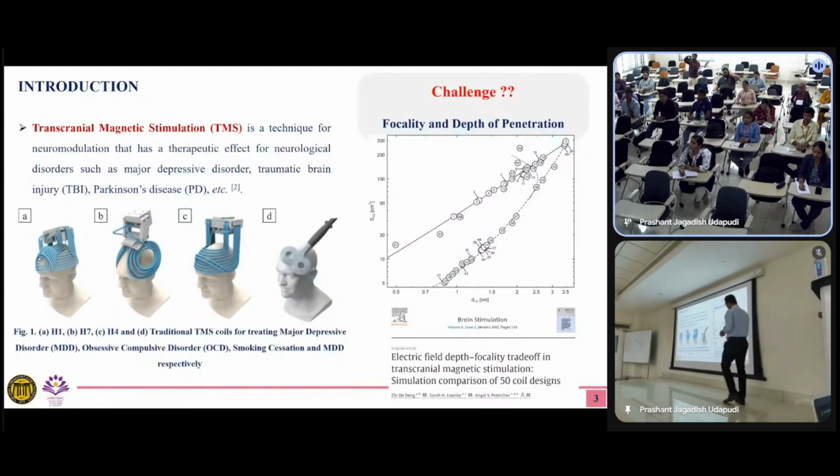So these are their commercial coils. In all these coils, there is no magnetic material. It's all copper windings. But the magnetic researchers know we can change the way magnetic fields are directed by using magnetic material. If you have high permeability, all the magnetic field will come through the high permeability material, right? So if you put a core here, all the field, instead of going below the coil, will go through that core, right?